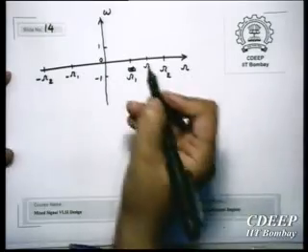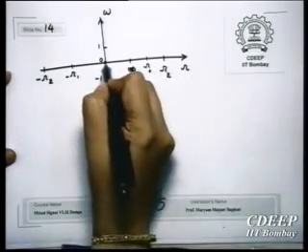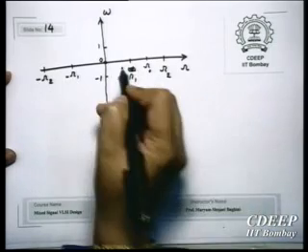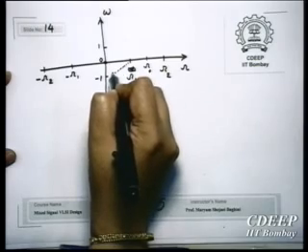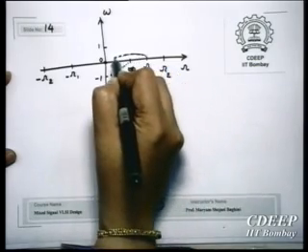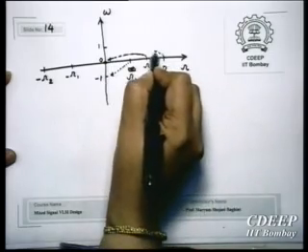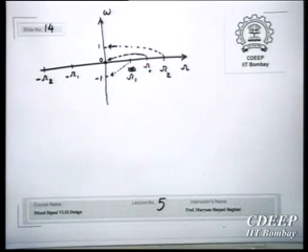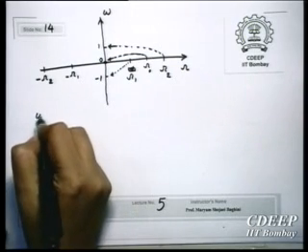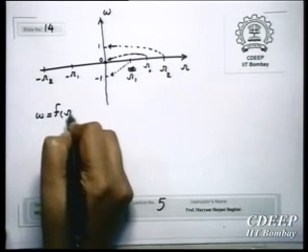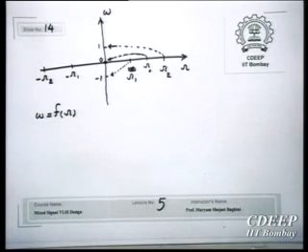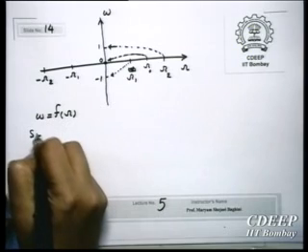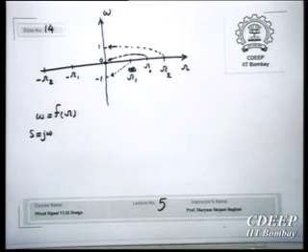And we have some center frequency, because I have to consider mapping to 0. So 0 was the center frequency. What we want to do is map omega 1 to minus 1, omega 0 to 0, and omega 2 to 1. So we have these 3 points. Therefore, we can just use a mapping of small omega as a function of capital omega to do the frequency transformation. One may say this is the omega domain and we want to use it in the S domain. This is okay, because S is equal to J omega, we will just replace omega by S upon J.